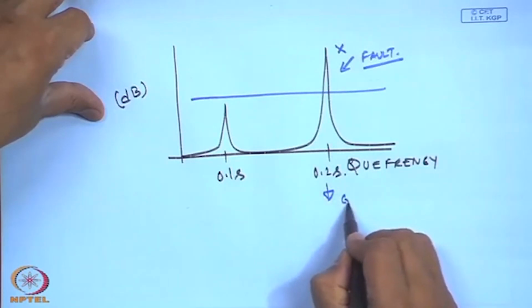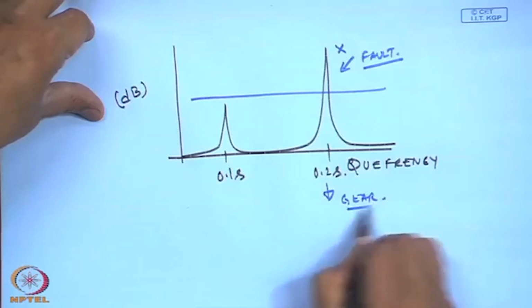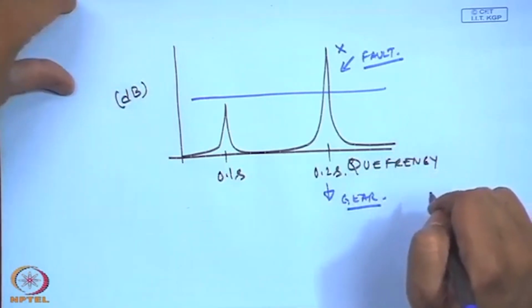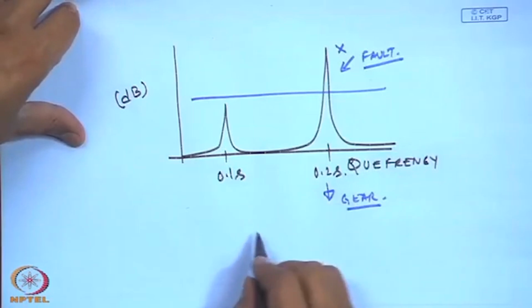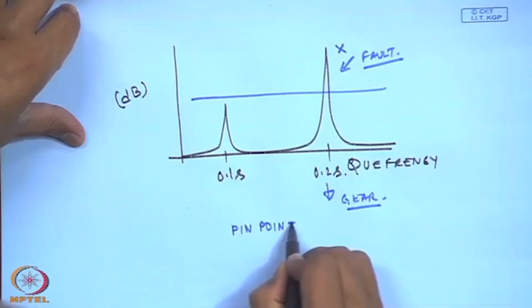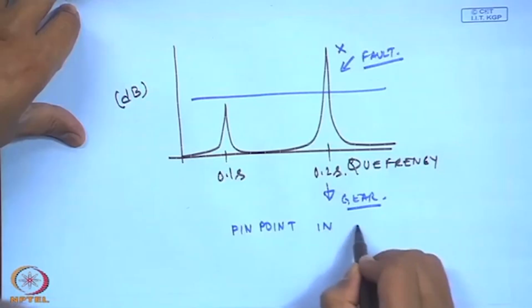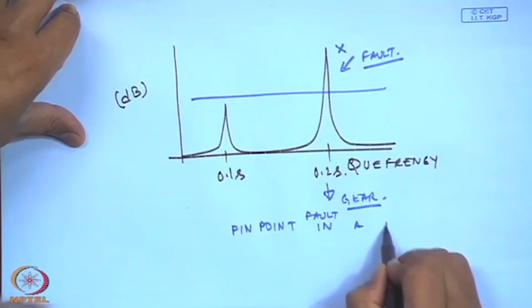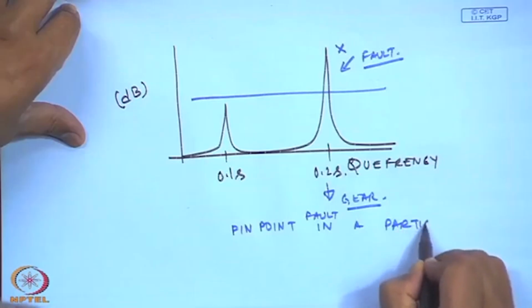In this case, it is my gear. Okay. So, we can use such a technique, cepstrum analysis, to pinpoint the fault in a particular component.